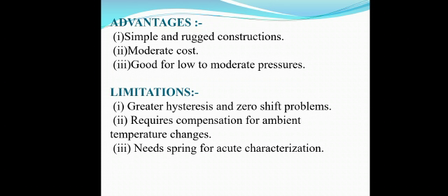Advantages: simple and robust construction. Second, moderate cost. Third, good for low to moderate pressure. Limitations: greater hysteresis and zero shift problems. Second, requires compensation for ambient temperature changes. Third, needs a spring for accurate characterization.